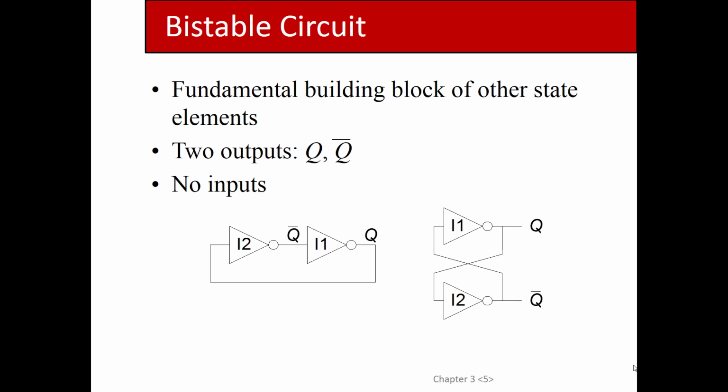That's pretty cool. And again, you don't have to use them both. By the way, this is essentially an SRAM cell. SRAM is the type of memory that you build caches out of, and register files and on-chip memory. And to this day, that's how they do it. It's just 2 cross-coupled inverters. The only thing missing from this is a way to inject a bit in, which in SRAM cells they use 2 transistors to do, but we're not going to cover SRAM cells.